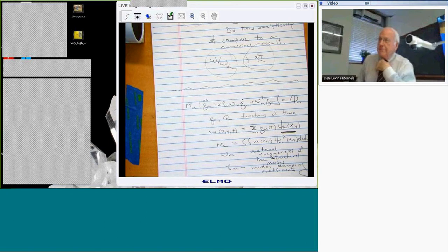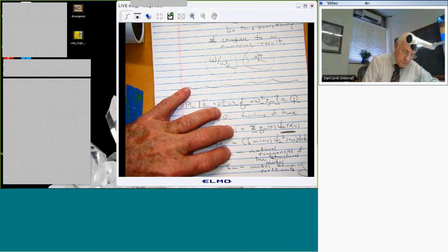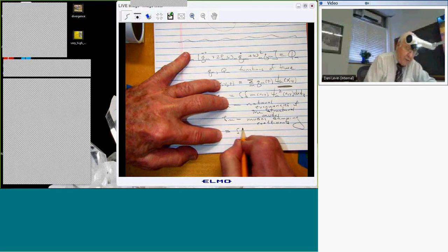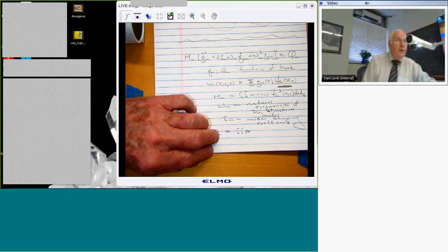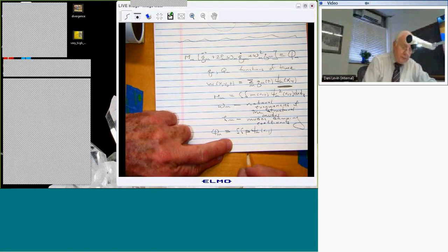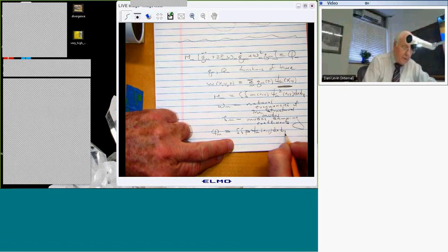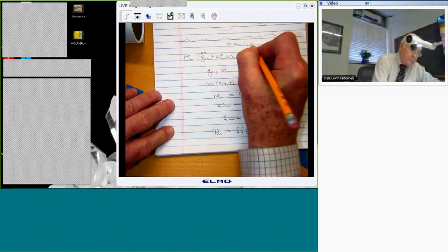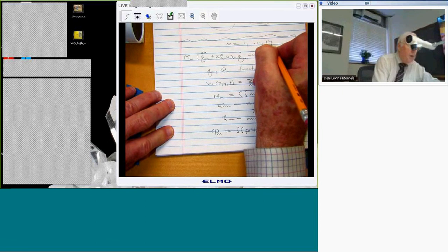And Q sub m will be the integral of the pressure, the force per unit area acting on my structure, times the relevant mode shape, dx dy. And how many of these equations do I have? Well, 17 modes. It would not be unusual to have 50 or 100.